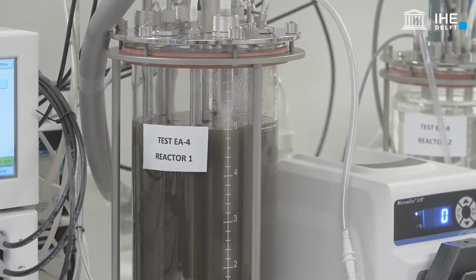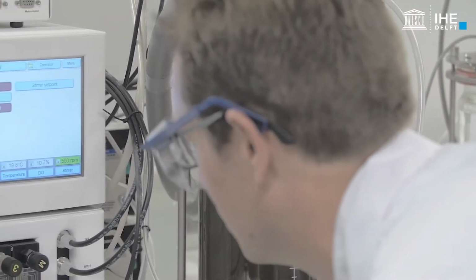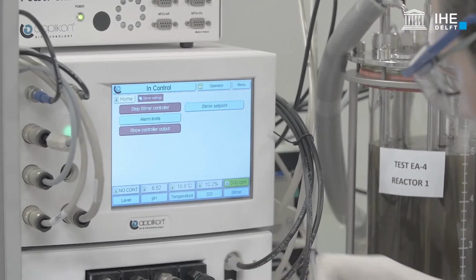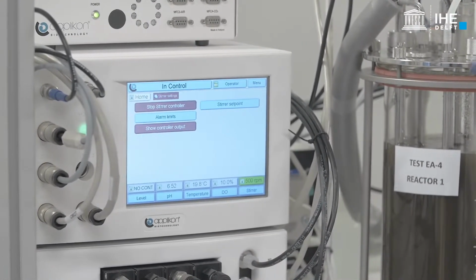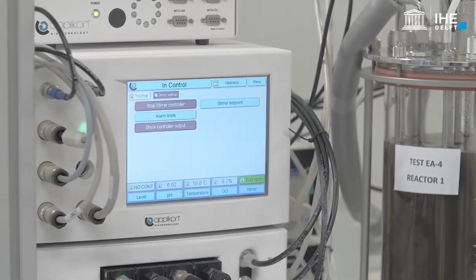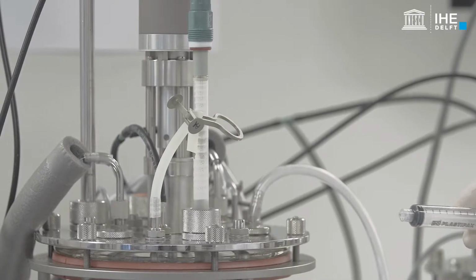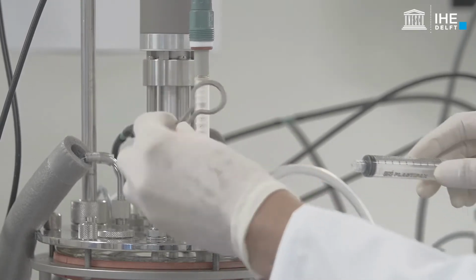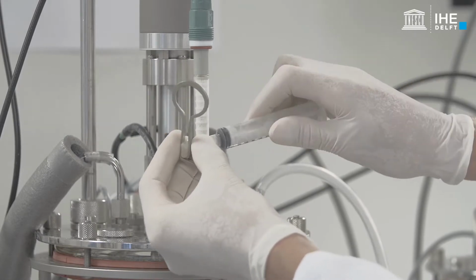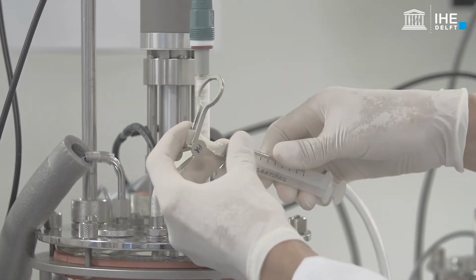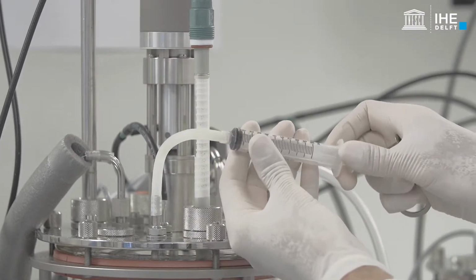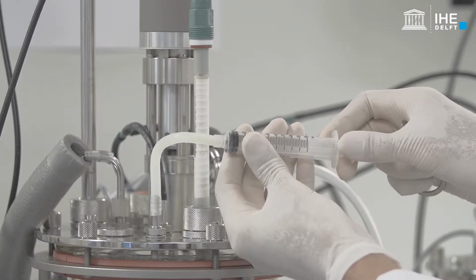Verify that the parameters of interest, like pH and temperature, are within the recommendable operating ranges. If not, correct and wait until they are stable and within the required allowable intervals. A preliminary sample can be collected to know the initial characteristics of the sludge. In particular, nitrate should be absent because it can interfere with the creation of anaerobic conditions.